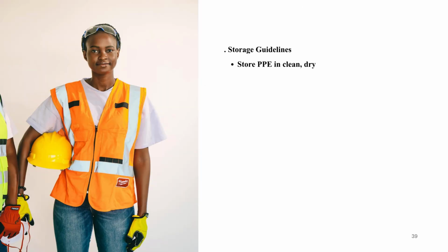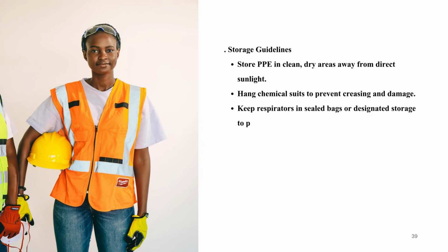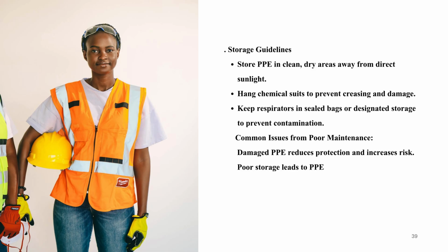Storage guidelines. Store PPE in clean, dry areas away from direct sunlight. Hang chemical suits to prevent creasing and damage. Keep respirators in sealed bags or designated storage to prevent contamination.